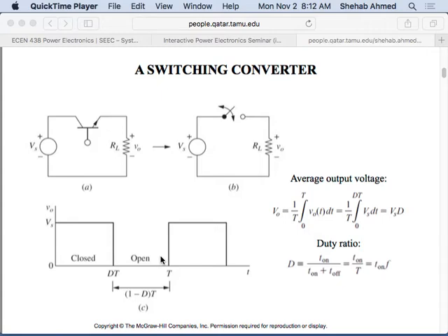Because motors have windings. The windings are nothing but RL series circuits. So these RL series circuits act like filters. Even though you're putting a pulsed waveform of voltage across the motor's windings, the current waveform is a nice, decent sine wave. Not pure, but a nice, decent sine wave. And we will see why that is the case when we talk about inverters in the next chapter.